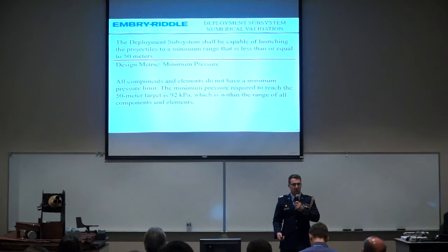Our design metric for this is minimum pressure. None of our components or elements have a minimum pressure requirement. The minimum pressure required to reach that 50-meter target is only 92 kilopascals, and we'll go over how we meet that in the next slide.